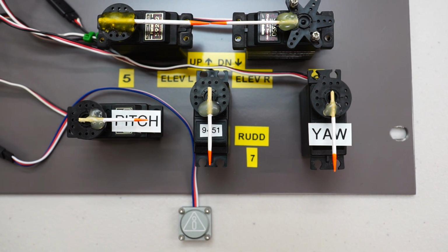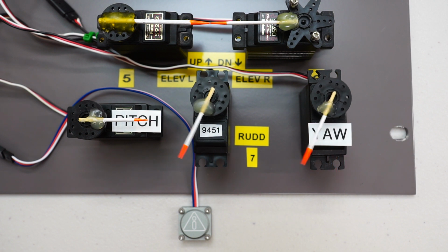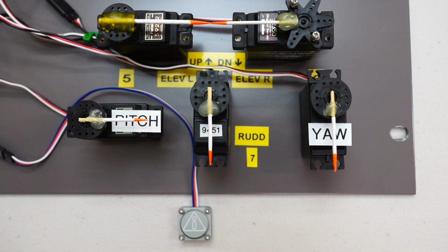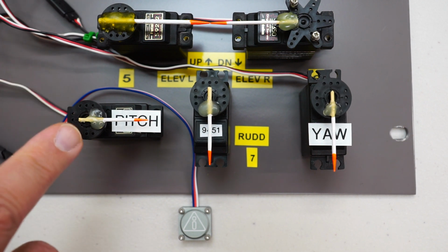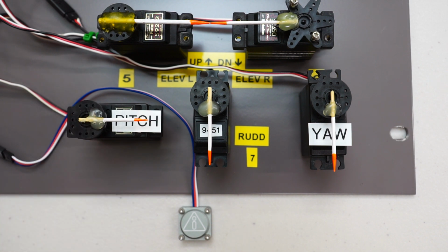Now, shown in front of the camera at the moment, I've got my existing model which we used in the part 5 video, which covered off setting up a vectored thrust model. Again, just to refresh everyone's memory, if I move my rudder stick, we have the rudder servo there in the center, and just to the right of it is my yaw servo, which controls the thrust vectoring nozzle. And if you remember from the part 5 video, they both have to operate in the same direction. That's the correct sense. And same goes for this pitch servo over here. This pitch servo is controlling the pitch, or the up and down movement, on our vectored thrust nozzle.